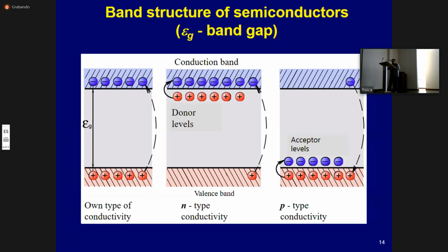These charge carriers, which are able to move under the action of an electric field, determine the intrinsic conductivity of the semiconductor detector. In real semiconductors, there are always impurities that affect the electrical conductivity of the crystal, because the number of carriers of electric charges increases. Impurities not only increase the total number of charge carriers, but can also change the ratio between the electron and hole concentrations. If the impurity atoms have one more